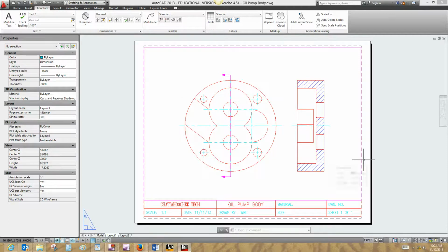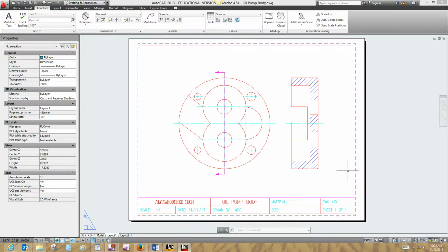Okay, so you want to make sure to place these dimensions in paper space. If you see a bold outline around your viewport, that means that you are in model space. Okay, and you can also see that you're in model space by looking down at the bottom of the screen and seeing model here. To get out of the viewport and work in paper space or the layout tab, you can double click outside the viewport. Notice it's no longer bold. Okay, also notice that this is now paper rather than model. You can toggle back and forth between the two also by clicking the button here.